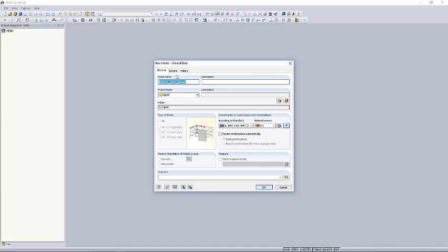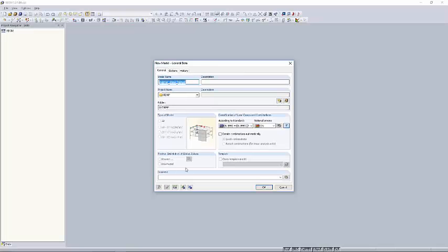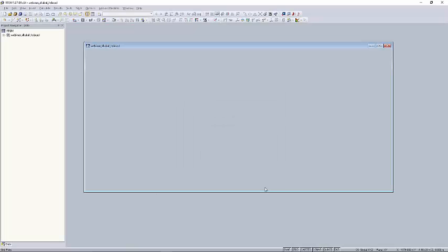Okay, with this option I'm able to create a CID BIM model. This is done by a coordination view 2.0 import. We are certified for the 2x3 interface with that, and what it does is generate an analytical system from a physical system that we get from the hsbcad software. It will create the combinations automatically according to the standard for the United Kingdom and create the structure.